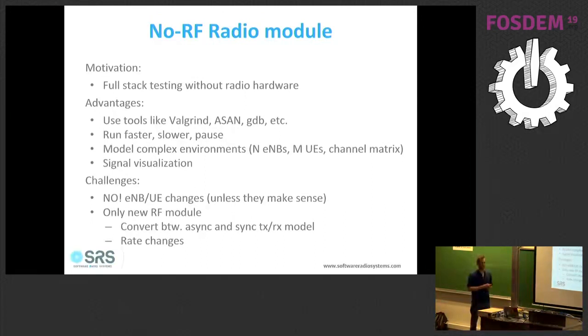But there are advantages to not using hardware during development, debugging and continuous integration. So something that we really want to do is to run the full software, but turn off the hardware. Run it with the PHY, but not do any hardware, and have those ideal signals, like Derek said. For instance, to be able to use tools like Valgrind or AddressSanitizer or GDB to really debug things without needing to get samples to the user or receive them.